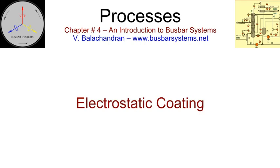Electrostatic coating. This process is very similar to powder coating. The bus bars are formed and fabricated with end preparation of the palm. The surface is subjected to buffing to remove all traces of oxide film, oil, and other contamination. The palms are masked with a heat-resistant tape. The bus bars are preheated in an oven for a specified duration and at a predetermined temperature.